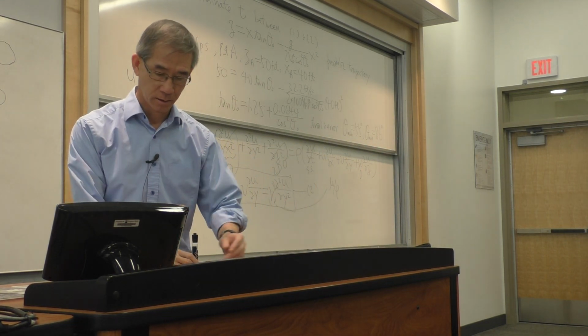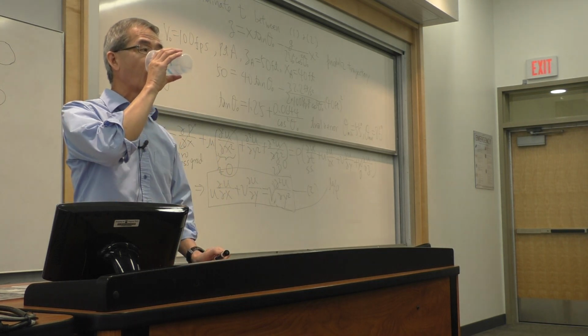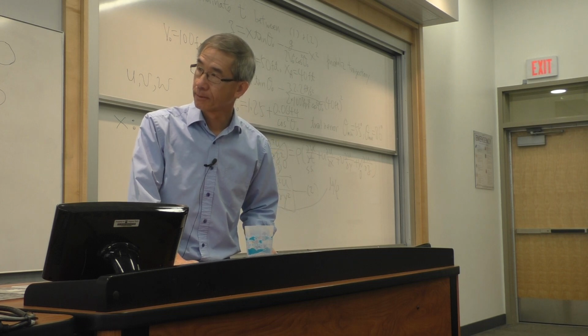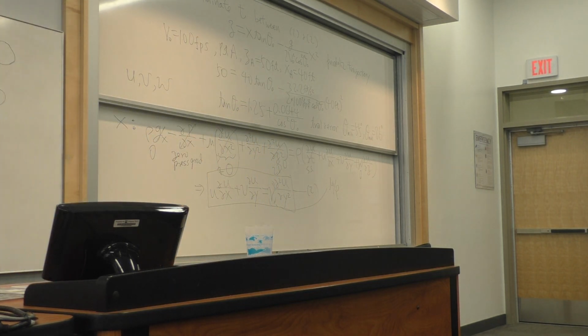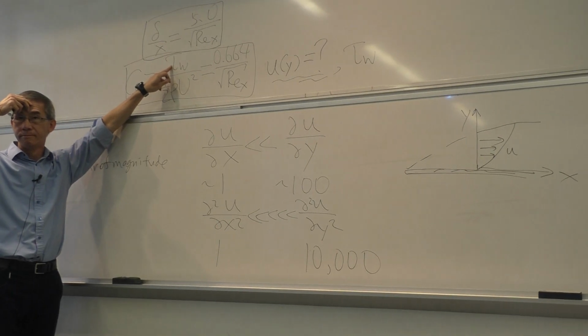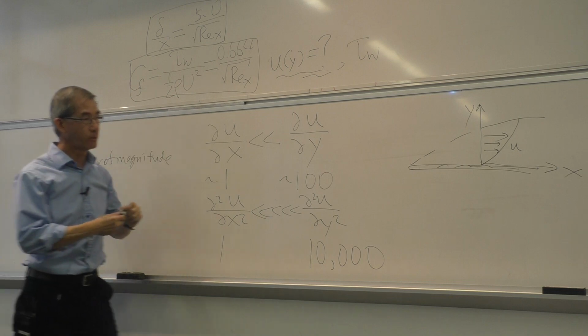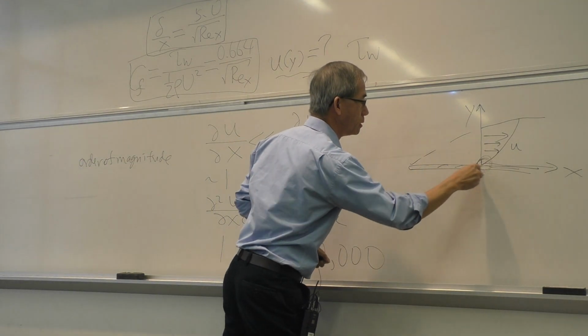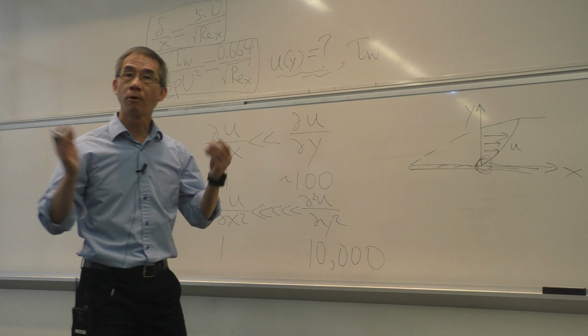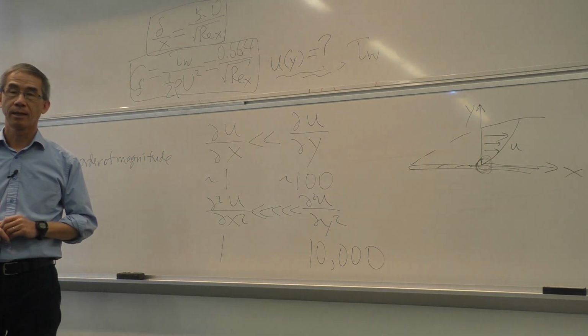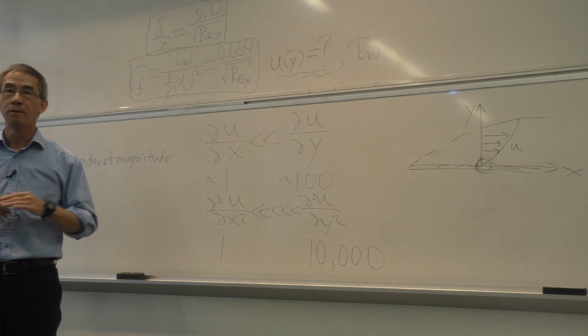Just one more question on that. When we have equations like that, where we have a friction, is that the friction coefficient? How do you get this? Anyone remember? du dy. Yes, you have to look at the derivative of the gradient right at the wall. It is the shear at the wall. At the wall, that's all you care about. That's what you want to estimate, how much friction is generated at the wall.